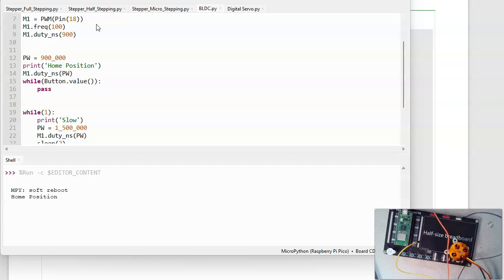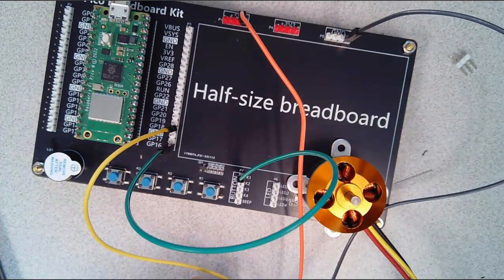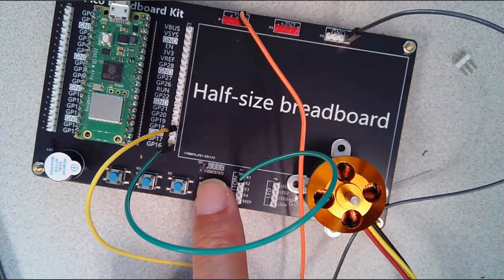What that did, that deedleet, deed, that first one, the deedleet, it's got power. The deed, it's got the correct power, 6 volts. The deed says it has the correct pulse width, 900 microseconds. So it is now waiting for an input. The input I want, I need a wire. It's waiting for pin 16 to go low, so I've connected up that wire. Hit the button.